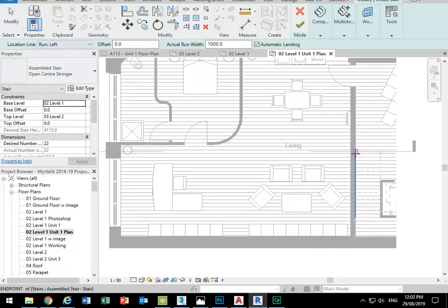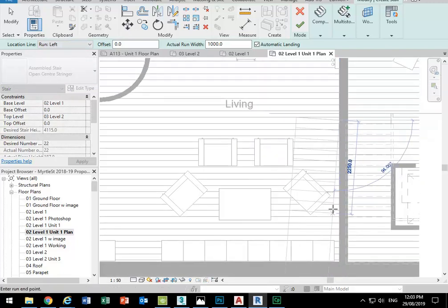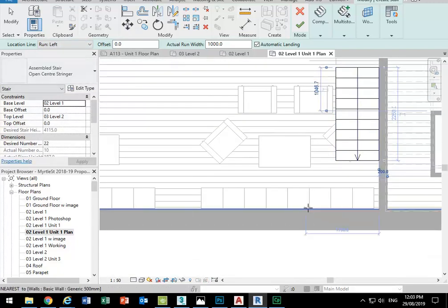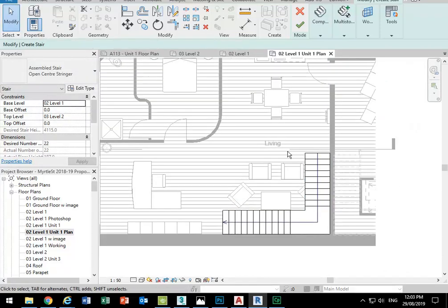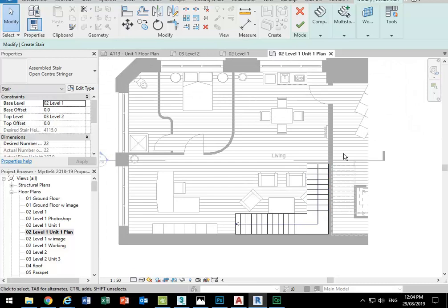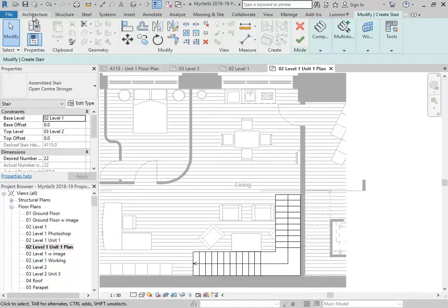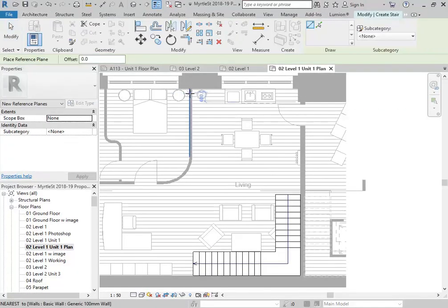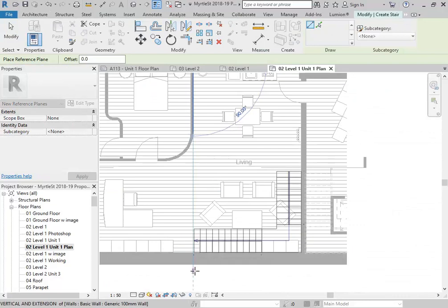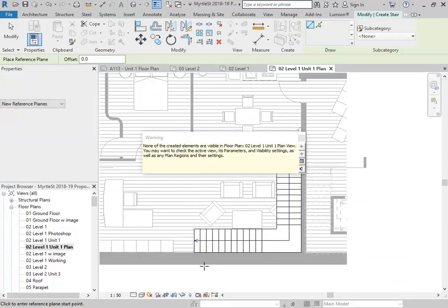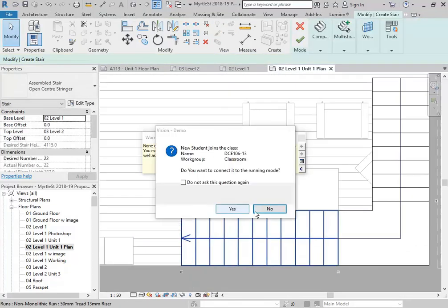Yeah, left is right, so that it makes more sense, or to have a layout that works with some void sort of open space. So above the living area there, I'll have a void, and actually maybe it'll make sense to have the stairs there line up with this wall, and then we're going to have a balcony coming up there. So, good trick there. Put in a reference plane and use that to align things. Well, what do you know, it's turned out pretty much in the right spot.